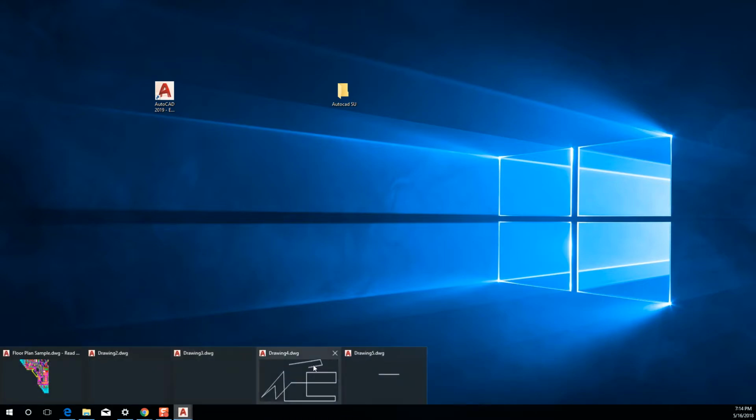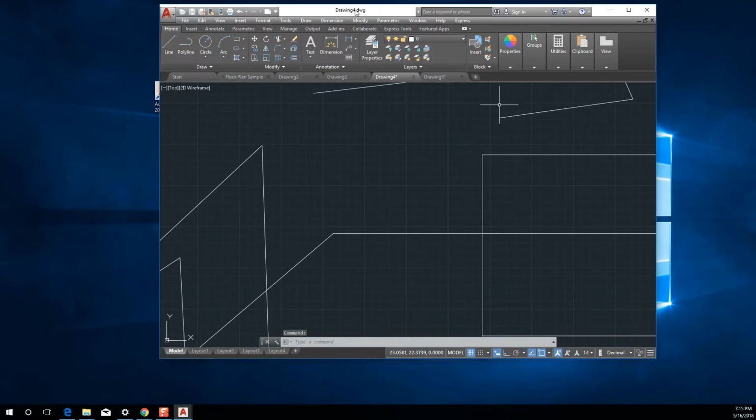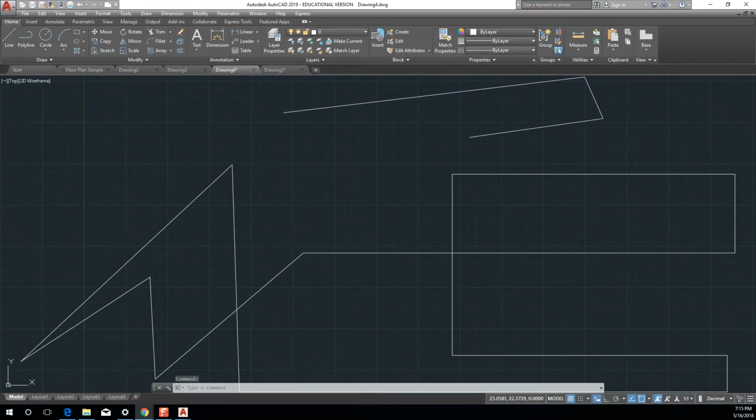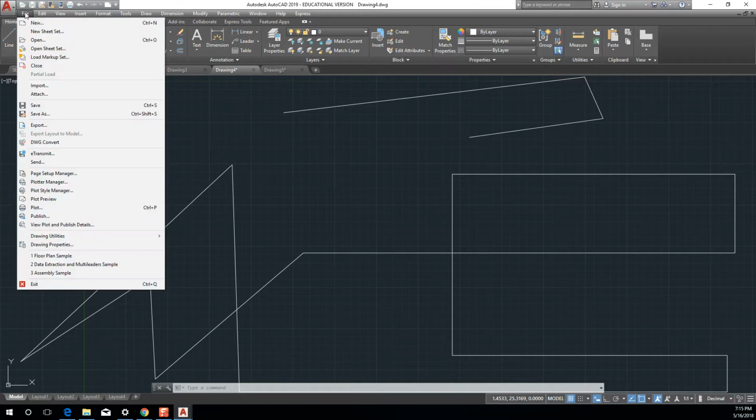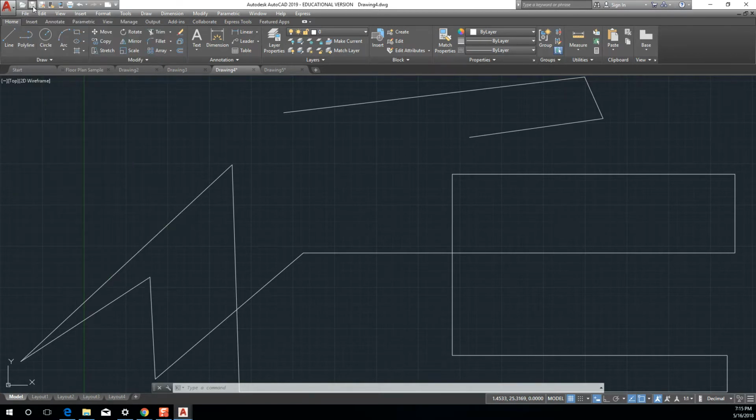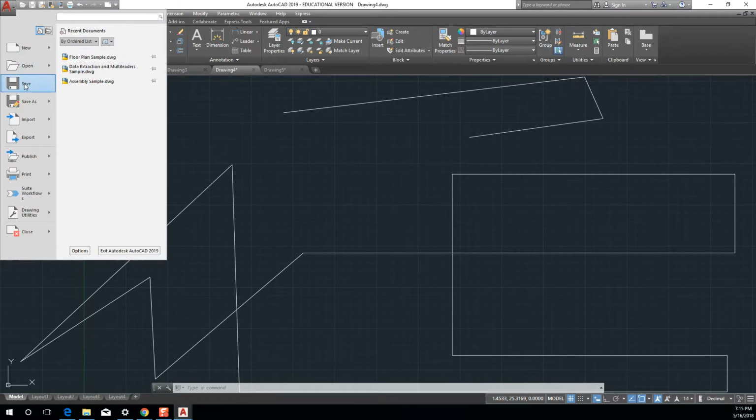And I want to save my AutoCAD file now. Okay. Let's see here. So the way of saving any file, everybody pretty much knows, right? We've got the Control S, which will save a file. I can come up here to File, Save, and that works. I can save with this little icon here. I can drop down and choose, there's about 19 different ways we can save a file in AutoCAD, right? I can type save at the command line and hit enter, and that will work.